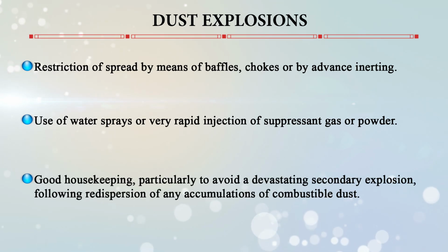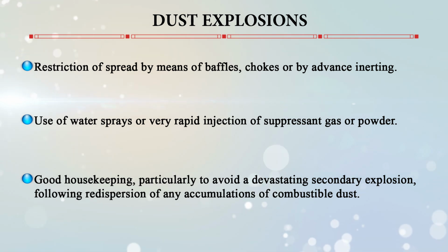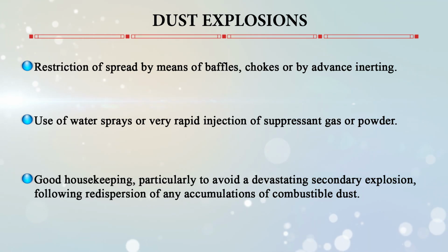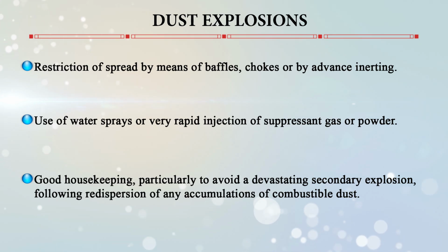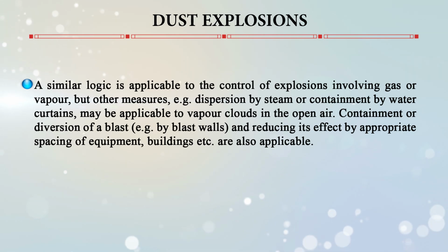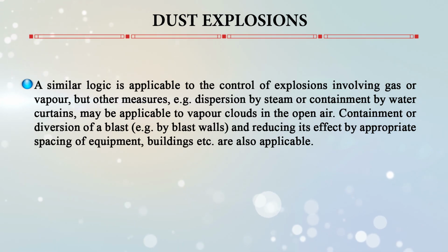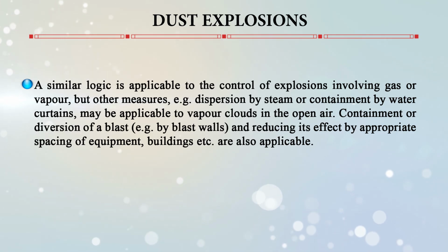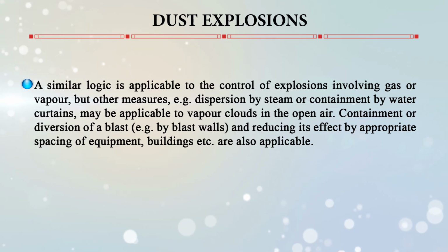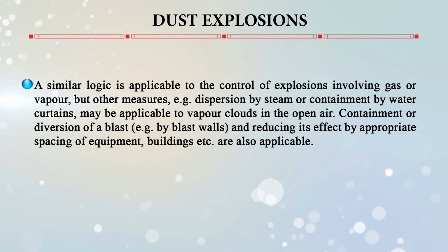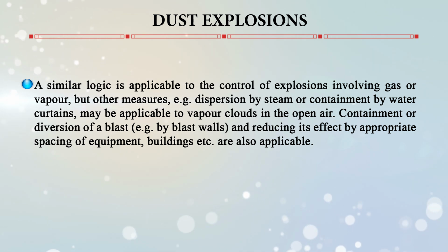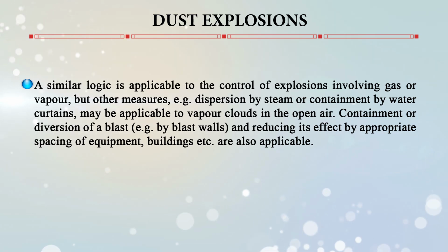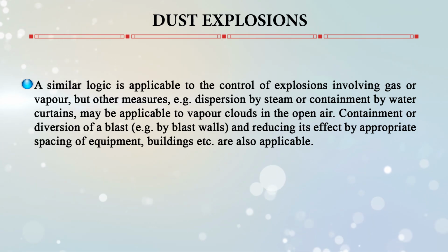And also good housekeeping is very much required, particularly to avoid a devastating secondary explosion which follows the redispersion of any accumulation of combustible dust. A similar logic is also applicable to the control of explosions involving gas or vapor, but other measures are also there, like dispersion by steam or containment by water curtains. They are also applicable to vapor clouds in the open air. So, containment or otherwise diversion of a blast, normally by blast valves, and reducing its effects by appropriate spacing of the equipment,